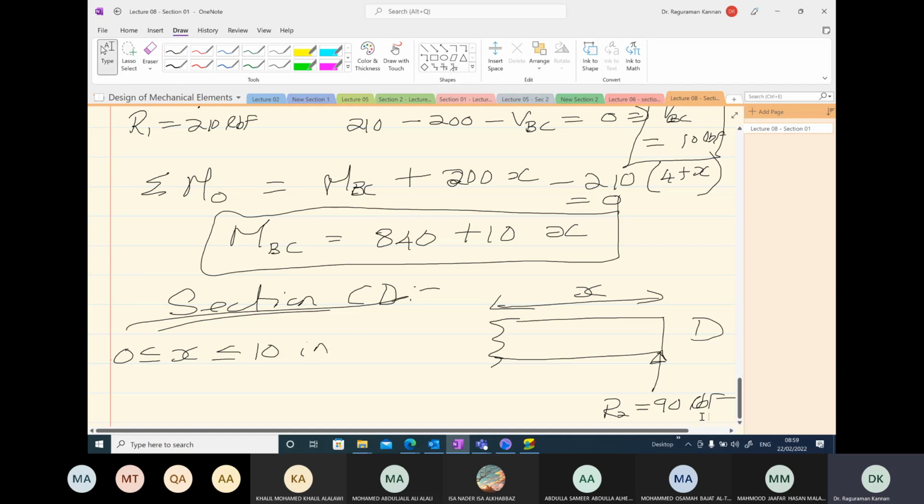We have to denote what are the reaction forces. Since we made a cut on the left hand side, my shear force is going up, leading to clockwise rotation of the beam. And then remember, for the blue color quantities, we are using the second sign convention to fix the directions.